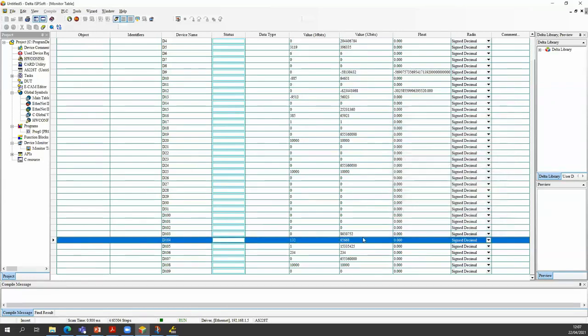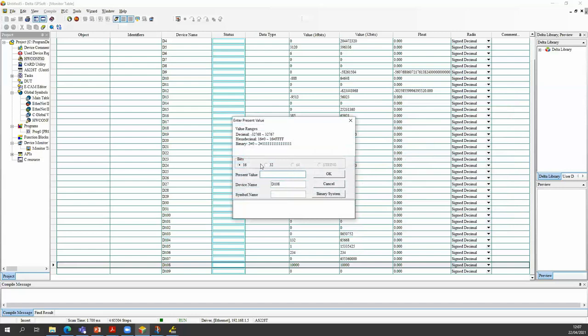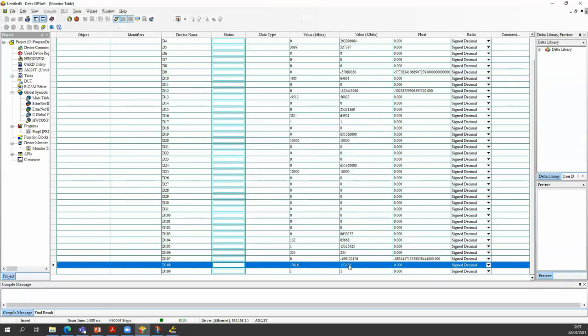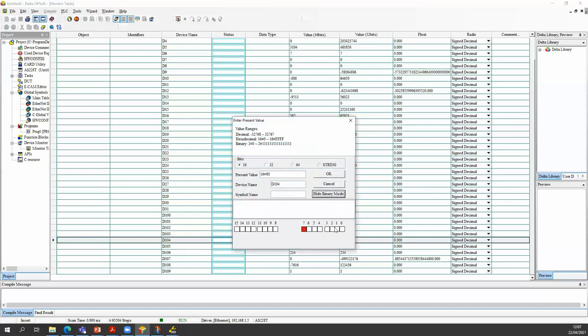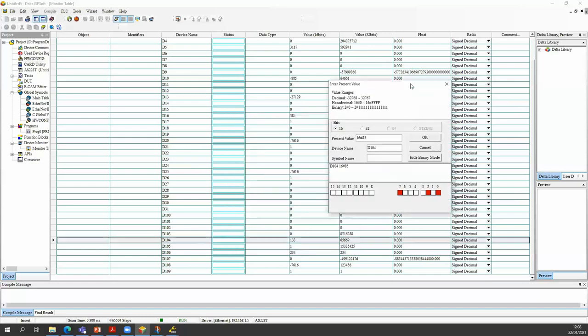Okay. I can also give it a higher position command. So I can set here a 32-bit value. So this will be 12 rotations. And you can see here the 32-bit value, which I've just written. And that's about it. You have different parameters where you can set the maximum point-to-point frequency, and also the acceleration and deceleration. All of these parameters you can find in our documentation.